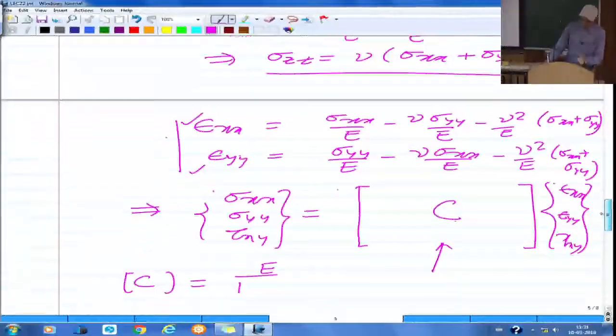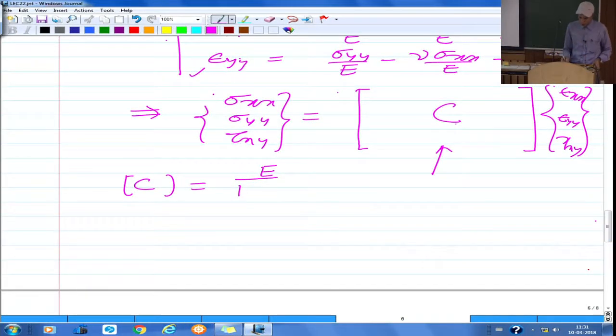So you solve this, it's a straightforward process, so you should be able to do that. Complete this, and next time I will also let you know. Once you have done this, there are two ways from here onwards. Either we develop the governing differential equations first, then the weak form or integral functional to be used for the element level governing equations, or, because it's a linear mechanics problem, we can write the total potential energy functional directly. So let me write that.